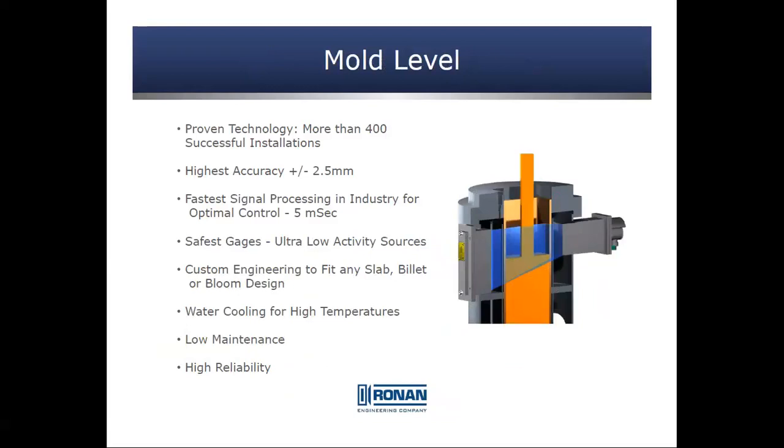For mold level, we have over 400 successful installations throughout the world. The highest accuracy we're able to provide is within 2.5 millimeters, and we're giving a process signal every 5 microseconds. We can custom engineer to fit into any slab, billet, or bloom design.